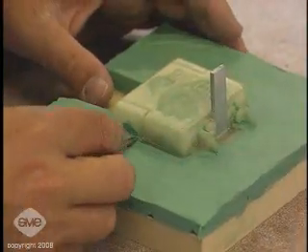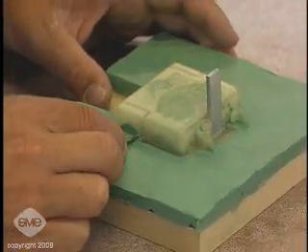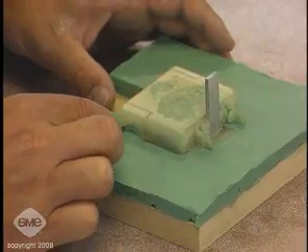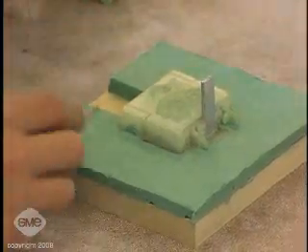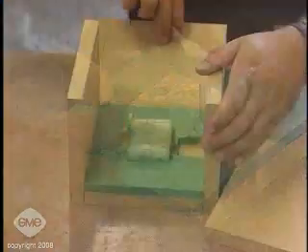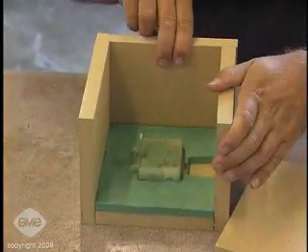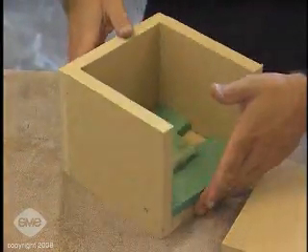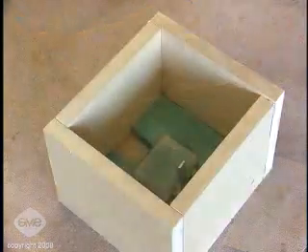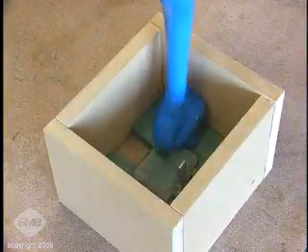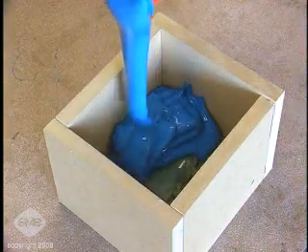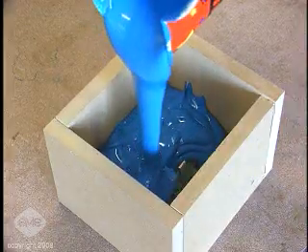Development of the first mold half begins by securing the pattern in oil-based clay or other building materials and constructing the parting line. Once done, the pattern is then secured in a box or frame. Silicone RTV molding material is then poured around the pattern and allowed to cure.